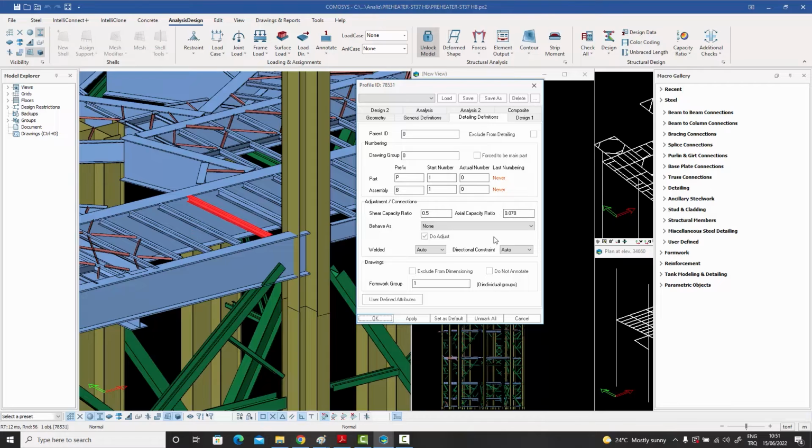This is actually not very small. This can be significant because we don't really want large axial forces in our beams. But sometimes you do have axial forces in the beams, so these can modify your choice of which particular connection to use. In any case, it's got two numbers in there, and now I can unlock the model, for example, and connect this beam with these forces.